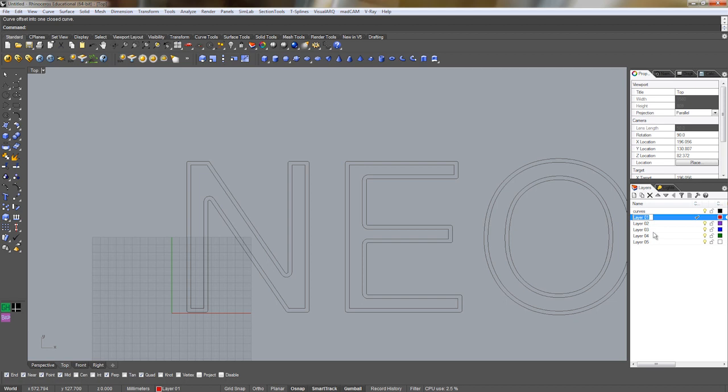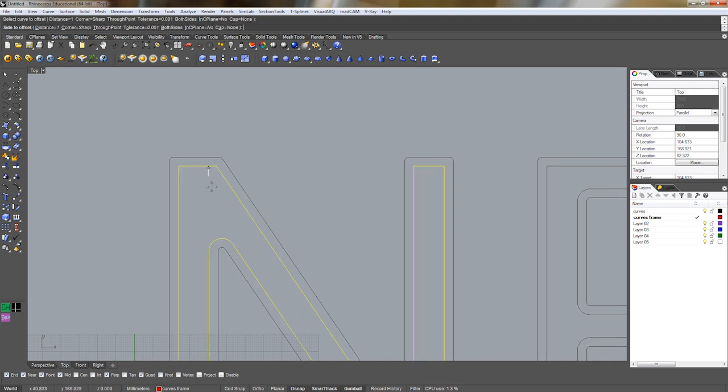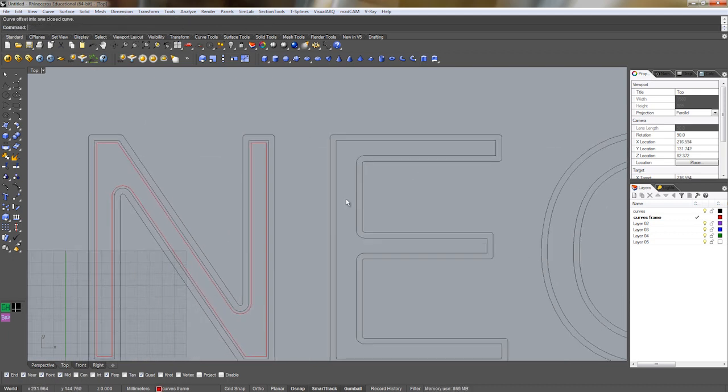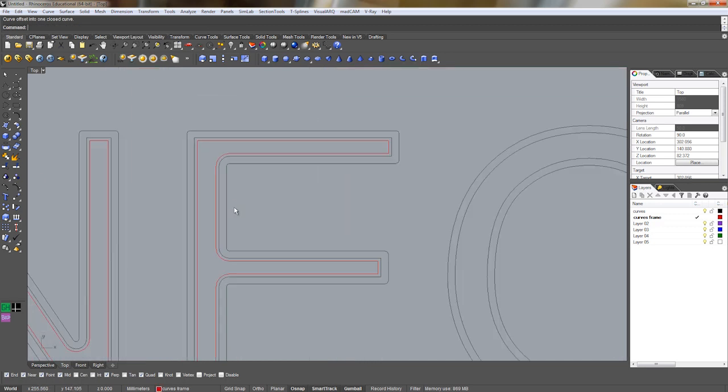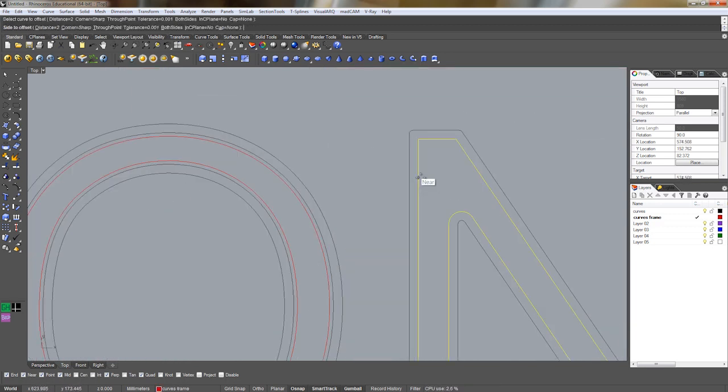Let's make a new layer for the glass frame curves. So curves glass frame, or just curves frame. Try to work always with a layer structure. Again, offset, this time only 1 millimeter, or yes, 1 should be enough. Let's make it 2 millimeters actually, because we're gonna fillet the edges there too. For the O we need 2, of course.